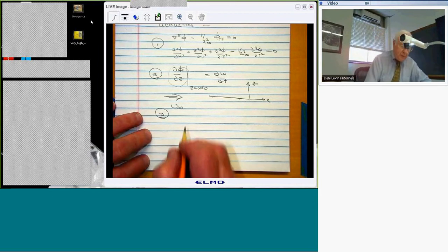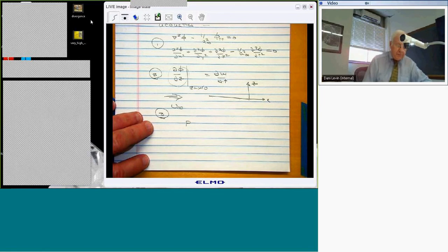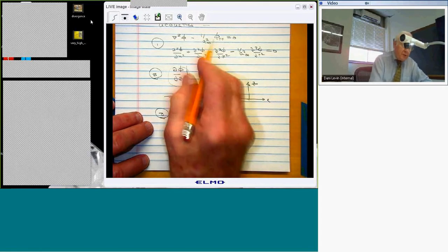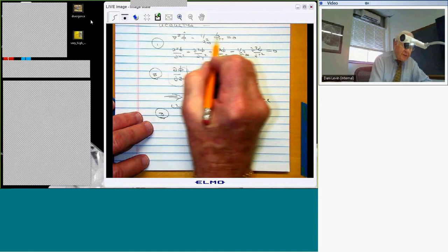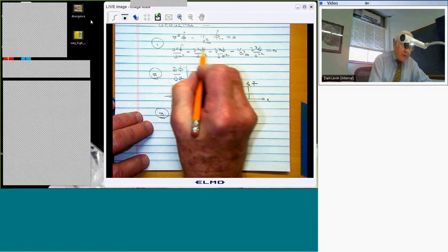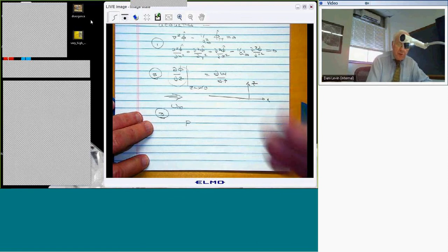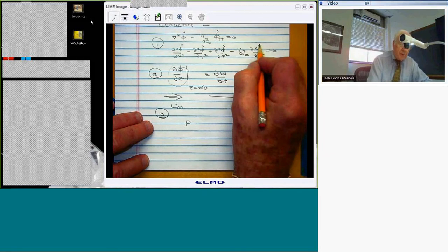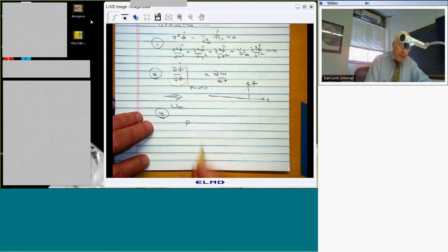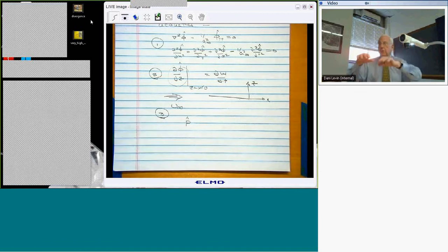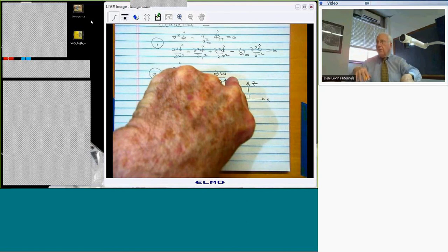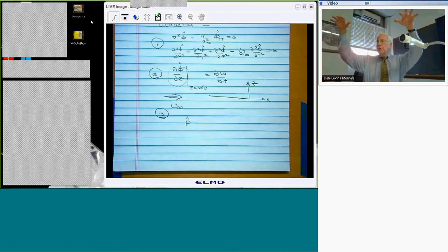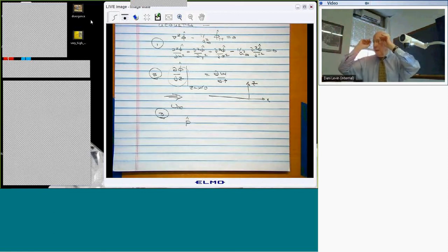constructed the following relation. He said the pressure, this is actually the perturbation pressure. In fact, I probably should put hats on all of this to indicate we're talking about small motions and small disturbances in the fluid and all that. The perturbation pressure, this is the pressure change due to the motion of this object in the flow, right? I mean, there's some mean pressure, which is usually called P sub infinity, right? That's 14.7 psi in this room.